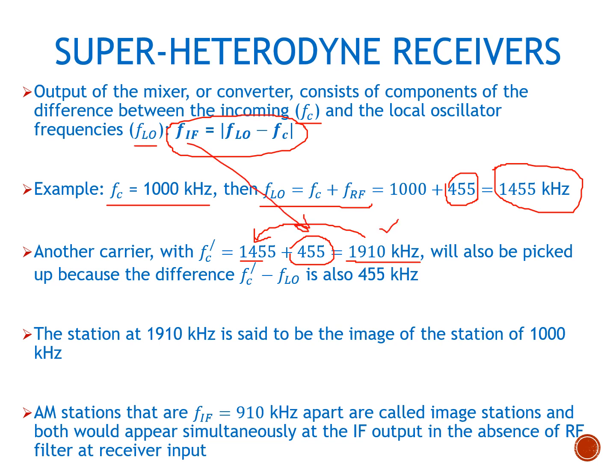So if we have a signal at the input having this frequency, then the IF would again be 455 kilohertz, and so this signal will also move to the stages that follow the IF down conversion stage. So that's why we would be picking two channels that are at very different frequencies.